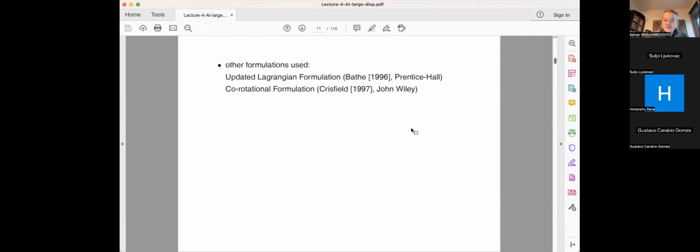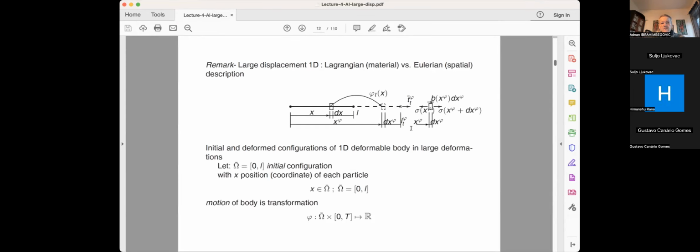So the frame is moving, and it's the same thing as in the structures that Mike Crisfield described in his book on structures. Well, we call this corotational formulation because typically you have a large rotation and a small deformation, and then you move the frame with the large rotation and you keep small deformation. So the end result is that you can take your finite element formulation for beam or plate or shell from linear theory, and you just wrap around it the large rotation of a frame, and that gives you something called geometric stiffness. We'll talk about that as we go along.